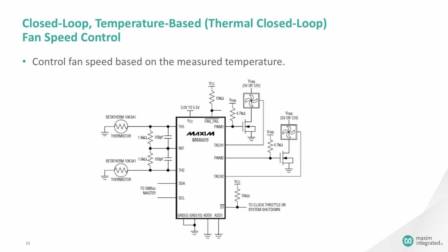Most fan controllers that have temperature sensing capability are also able to control fan speed based on the measured temperature. The details can vary. Most such fan controllers use some sort of straight-line mapping between temperature and fan drive, while others have a lookup table that associates a few temperature values with fan drive levels. Still others map temperatures to fan RPM values.